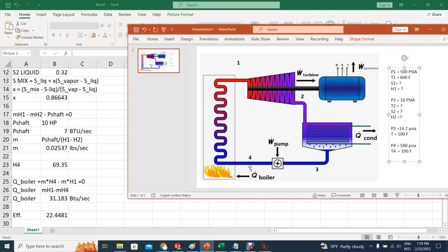It is indeed something, I mean, you need power, otherwise the pump would not work. But compared to what's going on between here and the boiler, this number is very small, even compared with the condenser as well. So again, that's the assumption that I made from 3 to 4, that the pump power here is pretty much negligible.